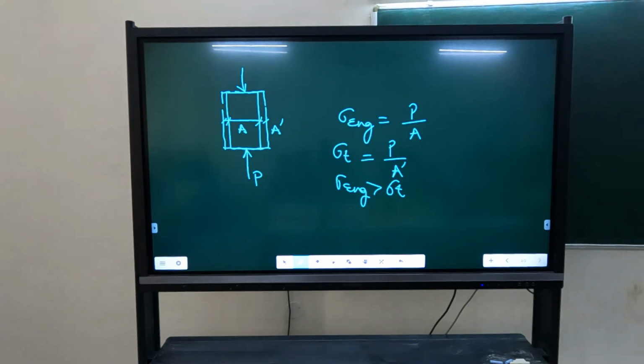Not the stress in the specimen. Stress in your calculation. Stress in the specimen is the same. Material will fail at a given stress. That is true stress. What you are computing may have error. So in computation, you have taken lower area than the actual.